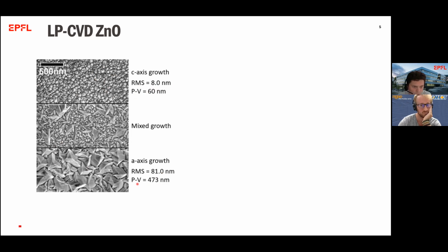You can see here a cross-sectional electron microscope image of such a solar cell. The greatest part is the glass, then there's some zinc oxide. We interject a small layer of aluminum oxide, the reason being that the ITO that we grow on top seems not to be perfectly impermeable, so we saw some side reactions. Those people that have tried to work with zinc oxide and perovskites before, or carefully follow the literature, know that zinc oxide tends to react with the perovskite in such a manner that you end up with just lead iodide or lead bromide.